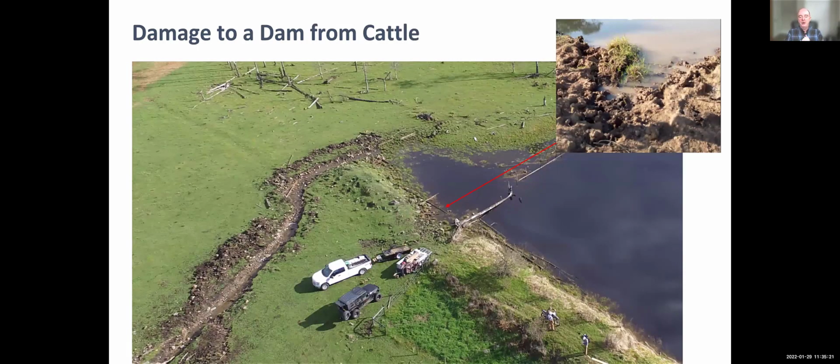We throw it in here, but a lot of our agricultural dams are in areas where there's cattle, and the cattle can wander around. And so if you get a lot of cattle traffic or quad traffic or truck traffic, there are various ways that you can damage your embankment through footprints and the erosion associated with that. And that's a photograph of damage on a dam from cattle.